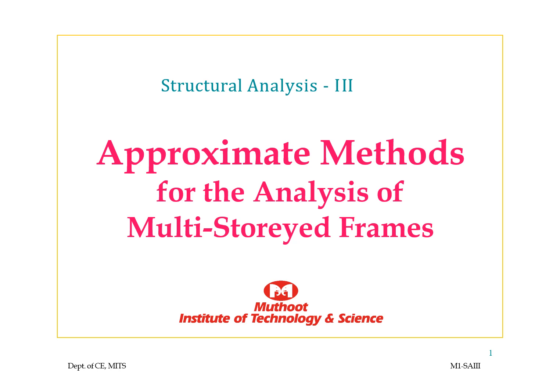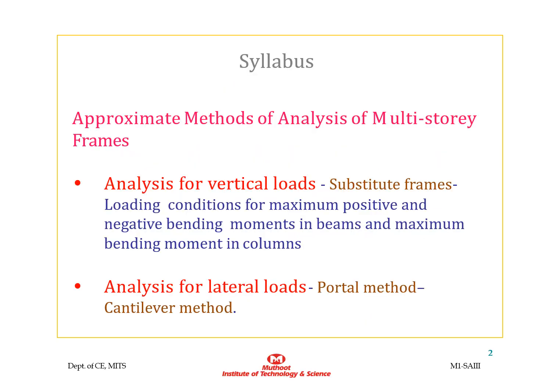Also, in the case of multi-story frames, the degree of indeterminacy, which we already studied in the previous semester, is very high. So the solution by the exact methods like slope deflection method, moment distribution method, Kani's method is almost ruled out. So, with certain assumptions, design engineers always use the approximate methods of analysis for a quick solution. In this module, we are going to study some approximate methods.